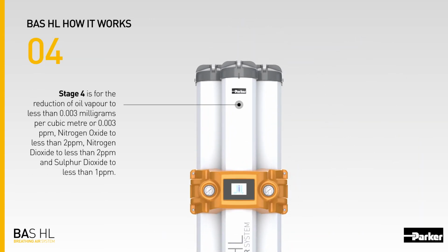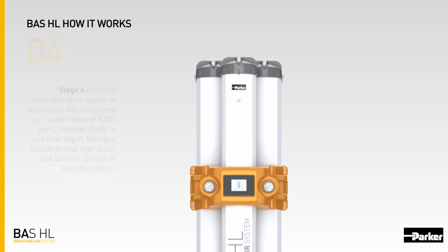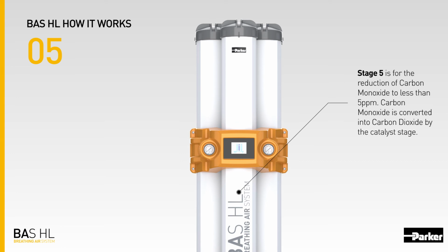Stage 4 is for the reduction of oil vapor to less than 0.003 milligrams per cubic meter, or 0.003 parts per million, nitrogen oxide to less than 2 parts per million, nitrogen dioxide to less than 2 parts per million, and sulfur dioxide to less than 1 part per million. Stage 5 is for the reduction of carbon monoxide to less than 5 parts per million. Carbon monoxide is converted into carbon dioxide by the catalyst stage.